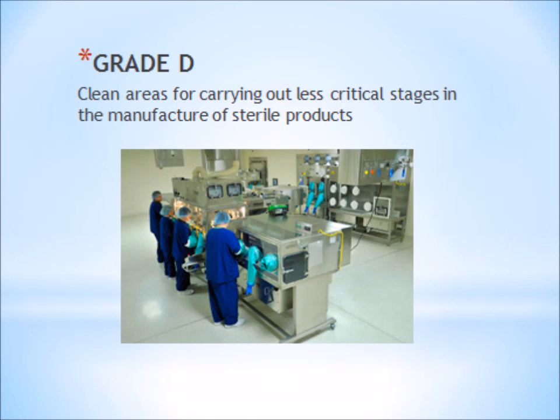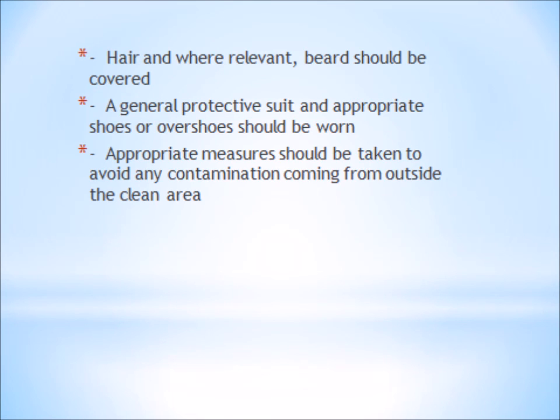Grade D. Clean areas for carrying out less critical stages in the manufacturing of sterile products. Hair and where relevant, beard should be covered. A general protective suit and appropriate shoes or overshoes should be worn. Appropriate measures should be taken to avoid any contamination coming from outside the clean area.